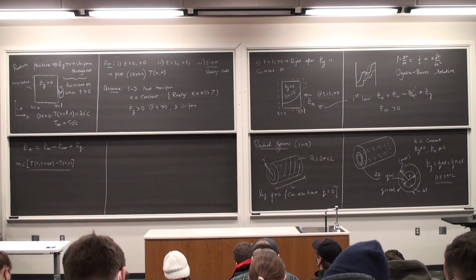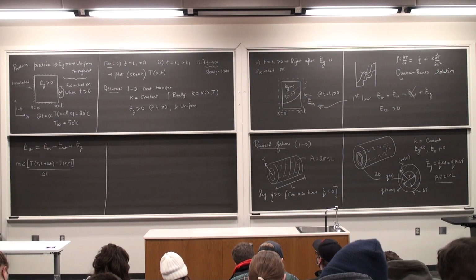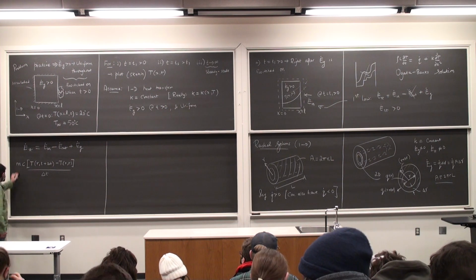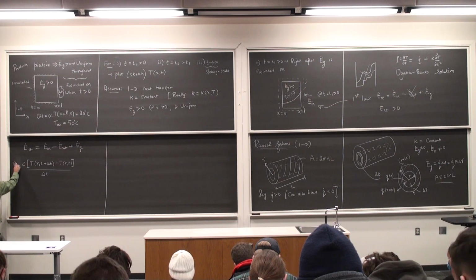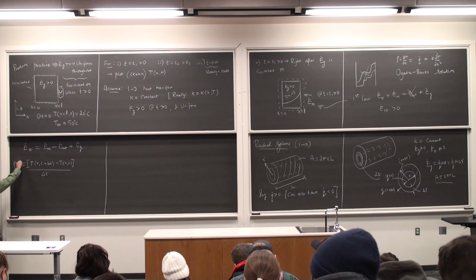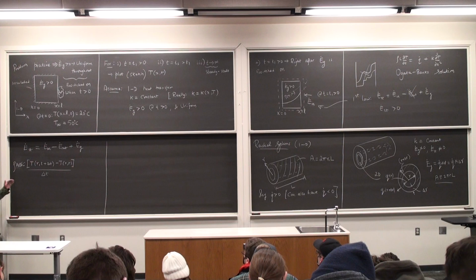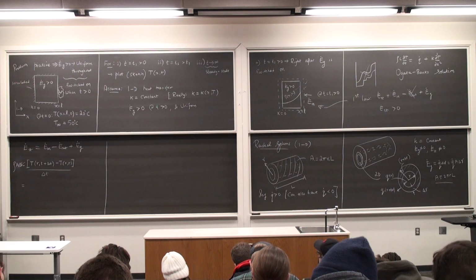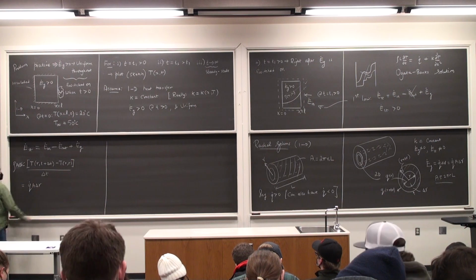Because it is a rate of change of stored energy, it has to be divided by delta T. This is what I have on the left hand side. Mass, we write it as density times volume. So with your permission, this is going to be rho times A times delta R, where I have substituted for mass as density times volume, and volume is area times the thickness. This is equal to E dot generated, which we write as Q dot times A times delta R.